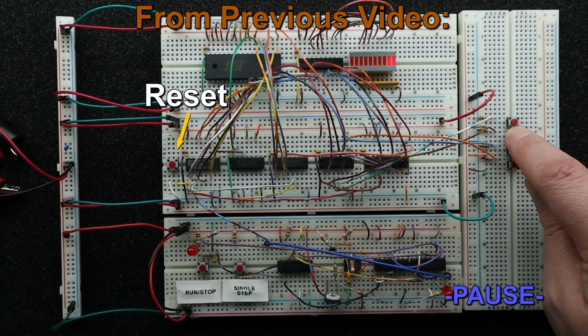The reset switch is connected directly to the clear pin of the IC for register A. So as soon as I released the reset switch, that register IC was taken out of reset. The main clock was already low, and since the reset switch was released, the decoder is enabled, providing a high from output number 1 due to the add instruction.